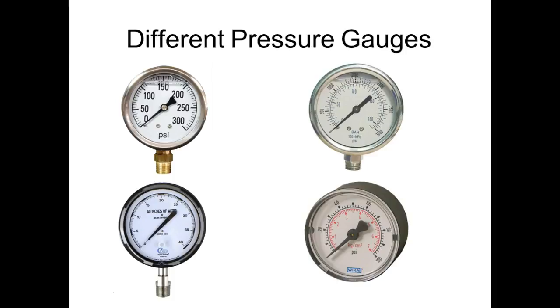So they charge a storage unit up to a maximum pressure, and then they turn the prime mover off until it drops below a minimum pressure. So if we're going to operate anything, we're going to operate it below the minimum pressure. If my compressor cuts off at 70 PSI, I'm going to buy air tools that are designed to run at 60 PSI, because that way 60 PSI is guaranteed.